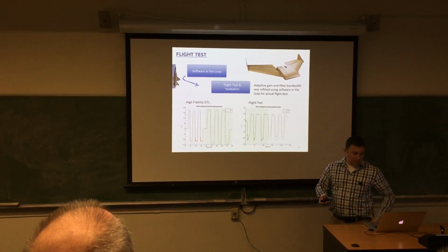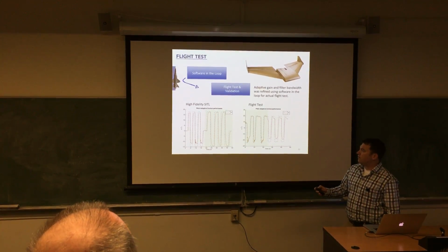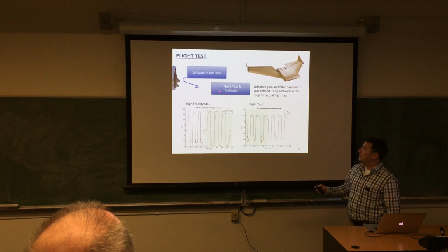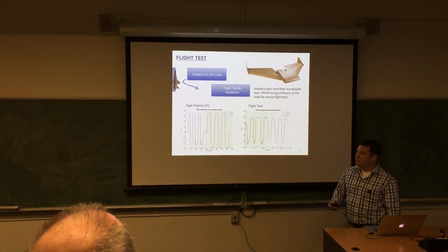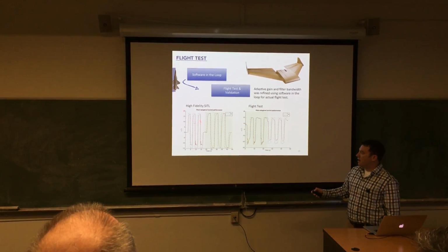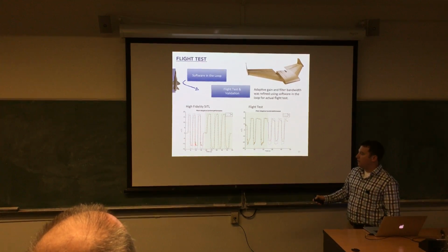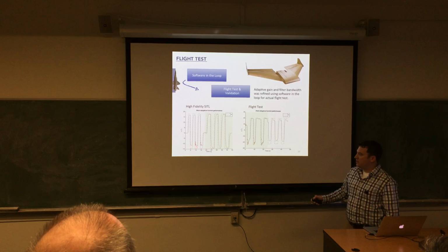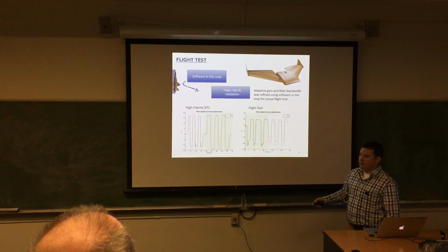So kind of the bread and butter of the results that I achieved. First thing I want to talk about is software in the loop going into flight test. So I used a software in the loop simulator called X-Plane. It's a very common aircraft simulation. And what I found was, in the pitch control specifically, for conventional control, you'll see there's this steady state offset. It never quite meets the demanded signal. But for the adaptive control, it was great. It was able to adapt.